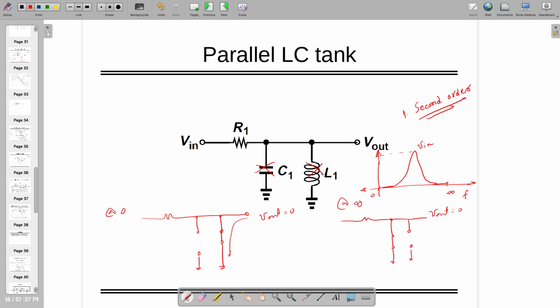If both are off, there will be one frequency where this will happen, and that is known as the resonance frequency. You can find it out by equating that to zero, right? So this is possible. Now tell me what kind of response it is. Band pass. Now if I want to create a notch filter, how can you make a notch filter? Just RLC with an RLC circuit.